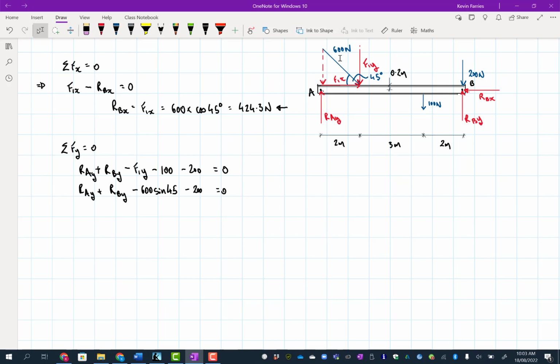Of course it is. Sometimes I get too busy thinking about what I should be telling you to think about the maths. So of course it's the same as this, because this is 45 degrees. So that must be 45 degrees as well, because they add up to 180. So you'd have 45 plus 45, 90 plus another 90 is 180. Therefore, these two angles are the same. Therefore, this is isosceles. Therefore, these two forces must be the same. Okay, that's where I'm going with that.